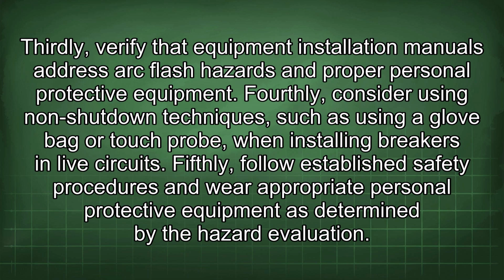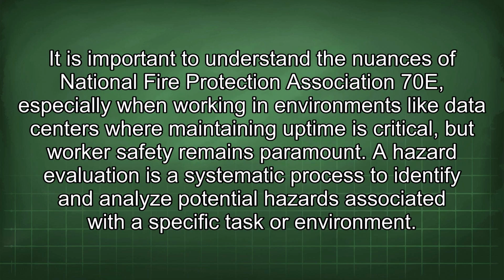Fourthly, consider using non-shutdown techniques such as using a glove bag or touch probe when installing breakers in live circuits. Fifthly, follow established safety procedures and where appropriate personal protective equipment is determined by the hazard evaluation. It is important to understand the nuances of National Fire Protection Association 70E, especially when working in environments like data centers where maintaining uptime is critical but worker safety remains paramount.